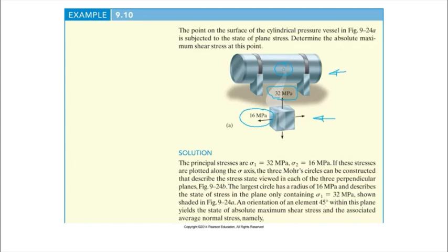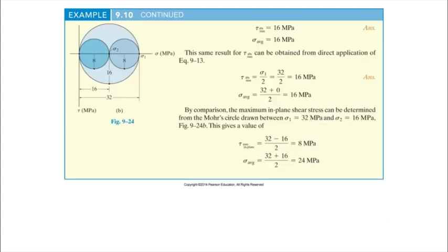Now, if you look carefully, there's no shear, right? There's no shear stress. Therefore, these two are the principal stresses. Okay, so we have two principal stresses here. The third one will be 0. Okay, the third one will be 0. So we can then plot on Mohr circle.